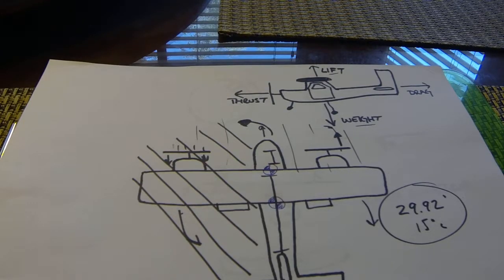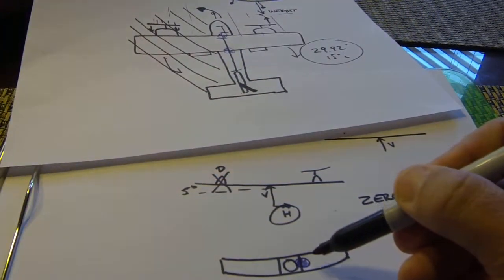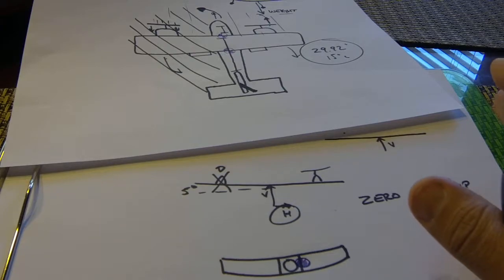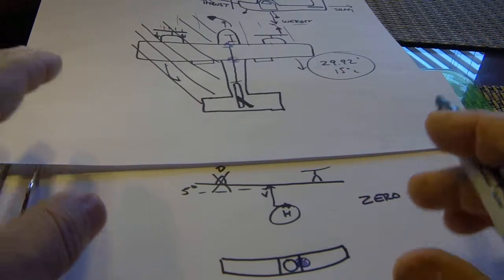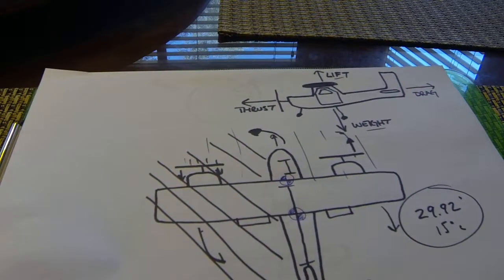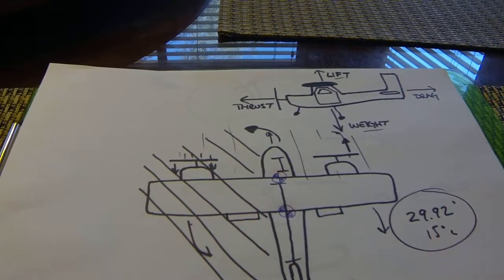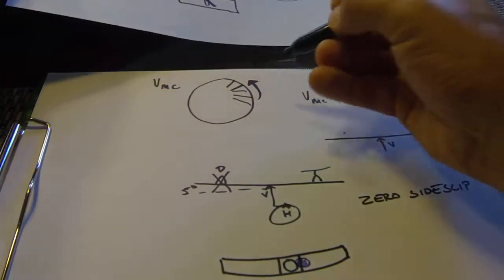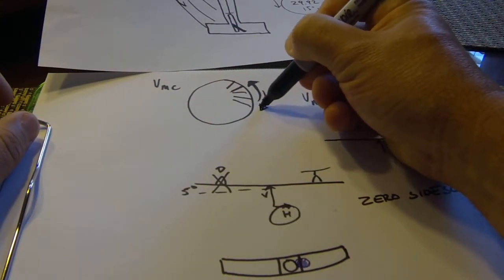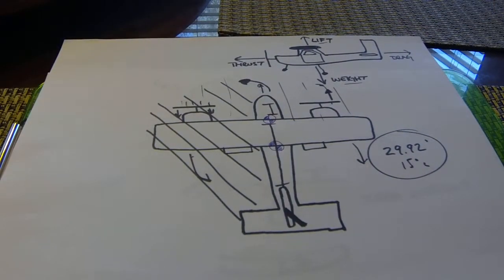So that's really important to know and understand, especially if we are in instrument conditions or at night. We can't really see the ground track or what's going on. Know and understand that we need to be up to 5 degrees into the operating engine and the ball in the inclinometer out of cage approximately a half. All right. Understand that, and we talked about it, in versus out of ground effect. If we are out of ground effect, we're going to have a higher VMC speed. All right. And again, it's just that cushion of air that we all know about.